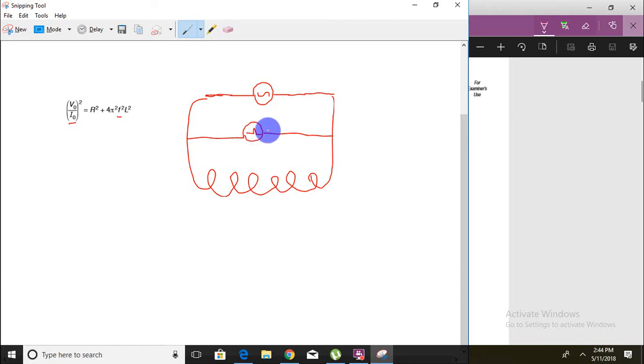So on the oscilloscope there would basically be a waveform. If the oscilloscope is properly calibrated with the help of the time base, there would be voltage on the y-axis and time on the x-axis. With the help of that we can confirm the frequency. We could measure the time period, and from that we can get the frequency and double check that it is the frequency that we set on the signal generator. At the same time we will get a value of the peak voltage, right? We can do that.